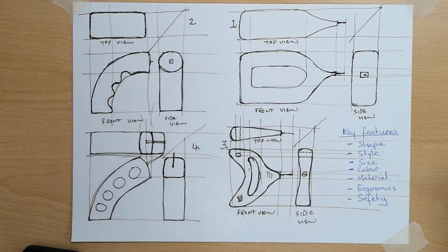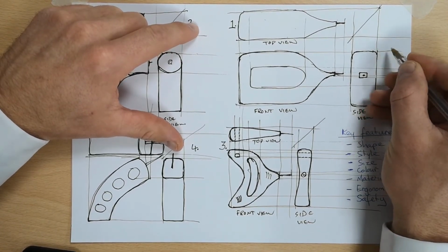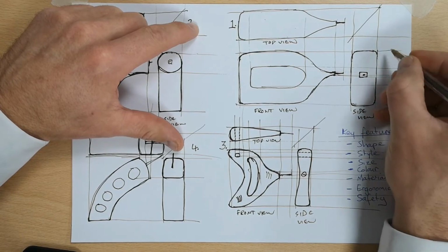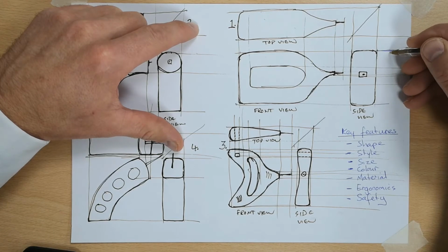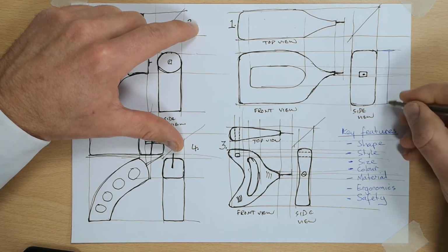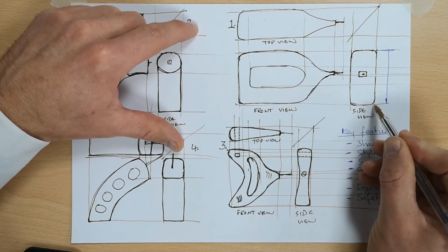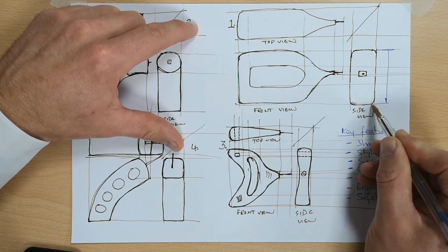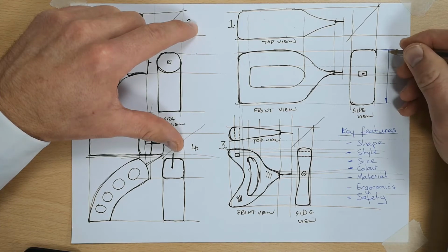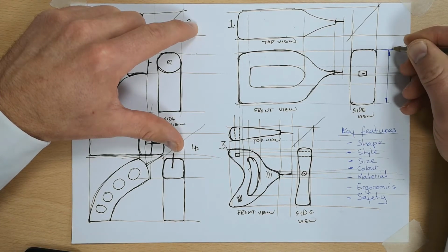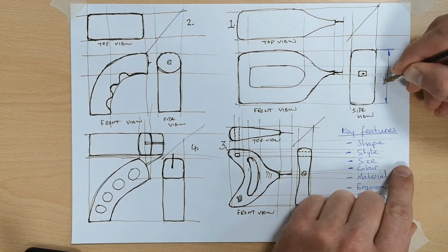So with the dimension lines, what we do is, first of all, we will draw, for the height of this side view, what's known as an extension line. The extension line comes out and away from the object. The extension lines go up to where you're measuring, but they don't actually touch. There is a gap here. They don't touch. So this is the extension line, this is the dimension line, and then this here is the measurement, 75.